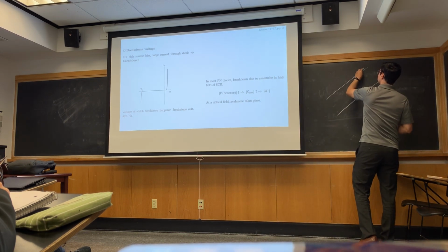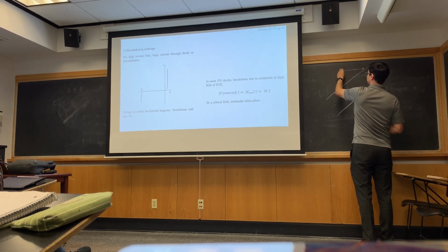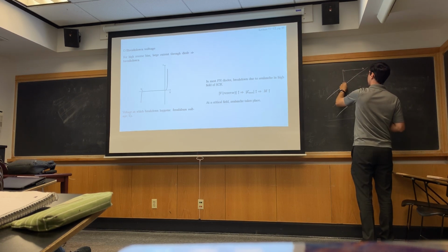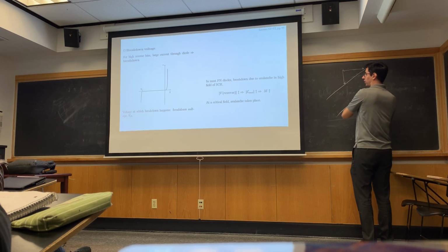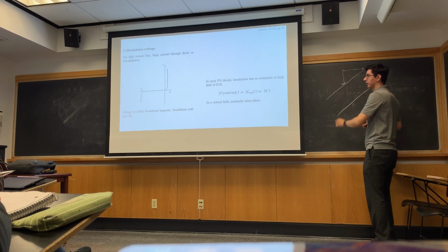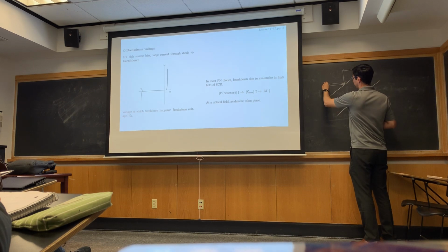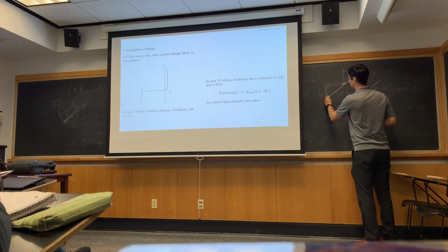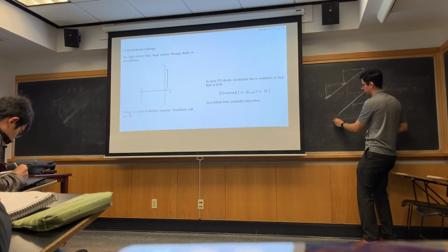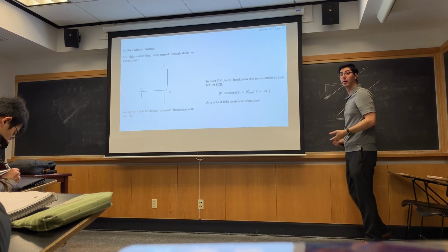I have one carrier. It gains a lot of kinetic energy. It has to gain kinetic energy equal to the band gap, at least equal to the band gap. It collides with the lattice. It loses its energy, but in the process, it breaks a bond, creates an electron hole pair. These two electron hole pairs can go and gain energy, collide with the lattice. Those two can now create 4. And this hole is going this way and can do the same thing. Okay? And so it's a snowball effect.